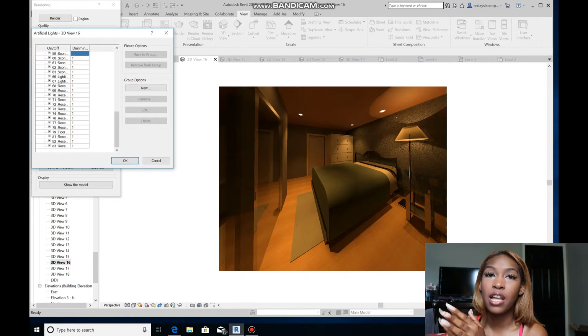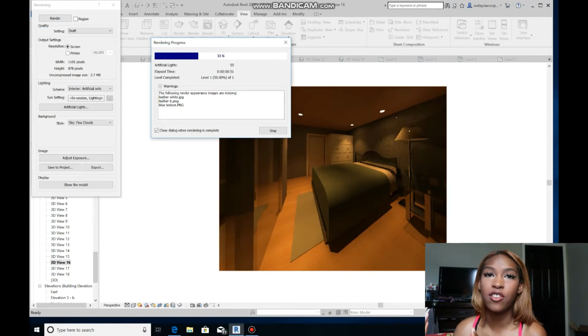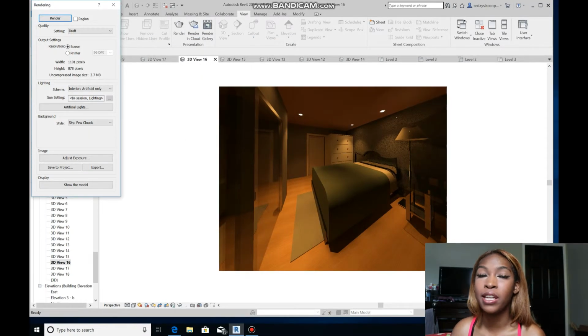I'm going to change the light from 1 to 0.0. Once I do this, the light seems like it turned off, but at this point it's just really dim. So again, this is something that you want to check, because as you're clicking through and manipulating the settings, you may accidentally change something. Always make sure it's at its highest capacity of 1 if you're facing any darkness problems.